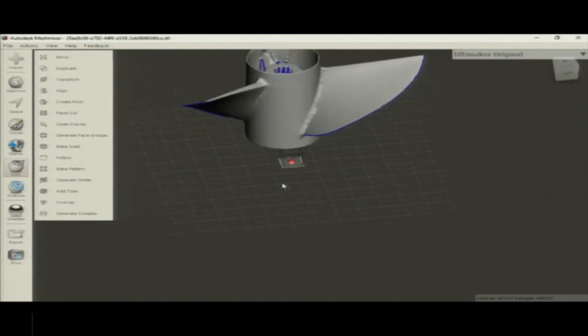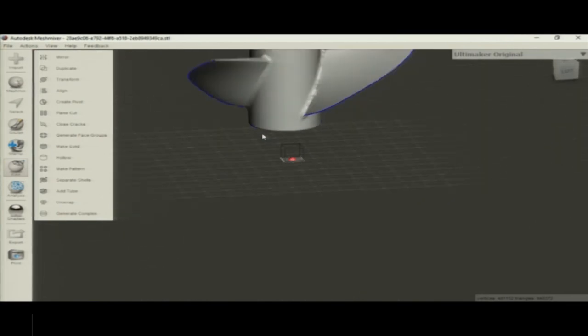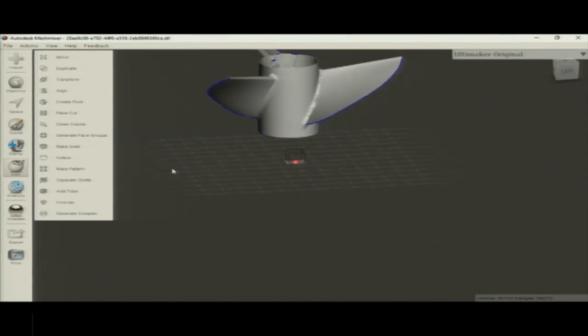See what is happening now. This is our 3D printer envelope, the small cube at the bottom. This is the 3D printing envelope, and this is the object. The object is of the order of 2 meters or so, and the 3D printing envelope is smaller. So we first have to fit this object into the envelope. We need to scale down the model according to our print volume.